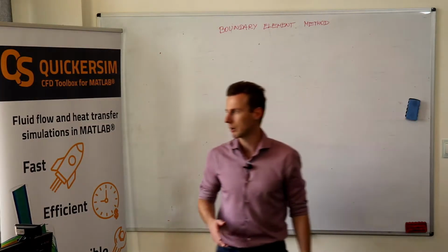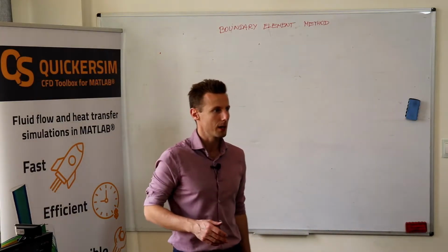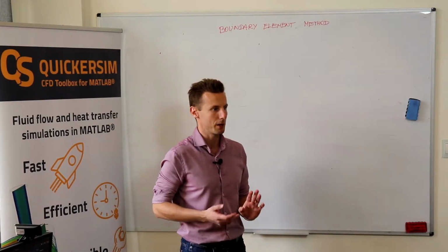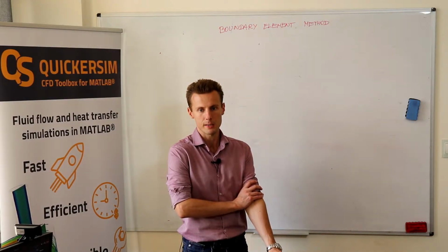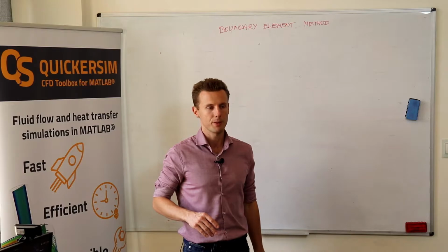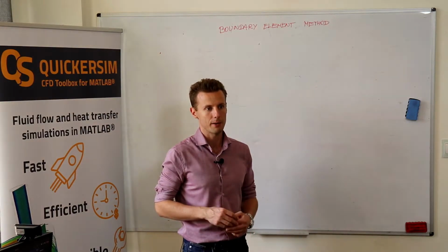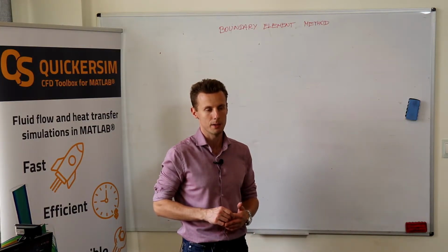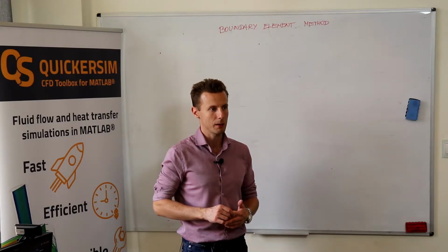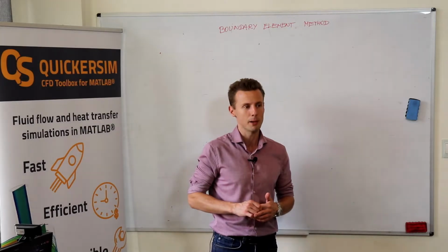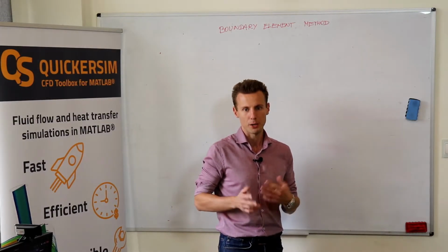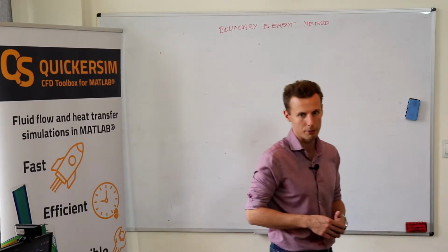Also, if some of you are interested in aerodynamics and aircraft simulations, then, well, not very popular right now, but in the 70s and in the 80s, external aerodynamics was calculated mainly with the use of panel methods. If you know the term panel methods, then panel methods are really just the boundary element method for the potential velocity field around an aircraft.